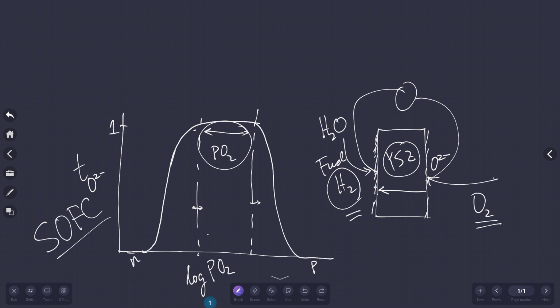Everybody talks about zirconia. Do you know why? Delta phase of bismuth oxide is stable only in a very narrow range, so it's not going to be usable. For some sensor applications with a limited range, you can use bismuth oxide. But for something like a fuel cell or a wider range of applications, that material is no good.